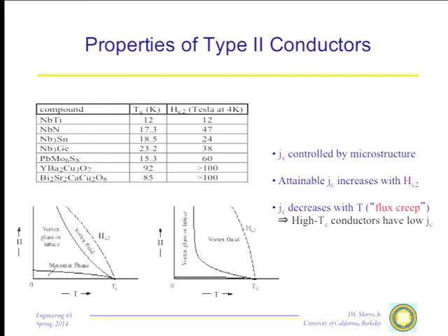Among the best, the thing that is still used, for example, for most accelerator magnets, and there's a big program up at LBL on accelerator magnets, is niobium-titanium, about 50-50. Niobium-titanium alloy is just an alloy. And it has the advantage, even though the properties aren't super great, a TC of 10 Kelvin, an HC2 of 12 Tesla, you can work this stuff. It's a ductile metal. And therefore, whenever you are making superconducting magnets you want to sell for prices that ordinary human beings can afford, they're almost always made out of niobium-titanium. The magnets they use for MRI treatments, and accelerator magnets in most accelerators, are niobium-titanium.